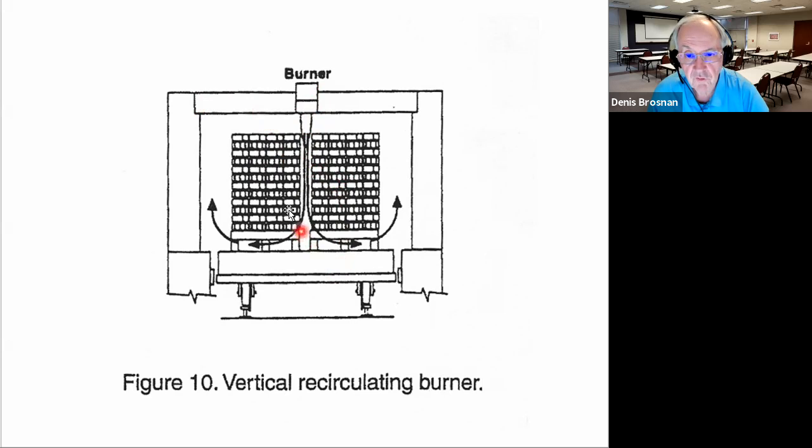So you're typically going to see a lot of burners in burner groups along the top of a modern tunnel kiln. So we're just trying to set these burners in such a way as to not have flame impingement and also to push the heat down. We're fighting the buoyancy of the hot gases when the burners are firing.